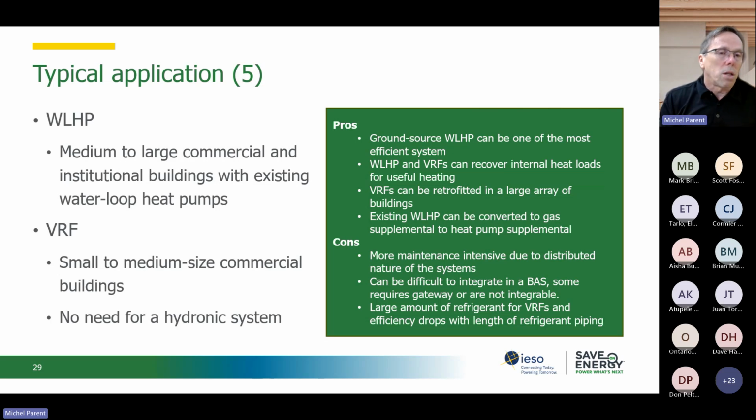So we have the pros and the cons for that type of application. A VRF system, by the way, the pro is really that it's a fairly easy retrofit. You don't pass water lines, it's just small refrigerant line. It does not do a whole building, but you can add multiple VRF systems. There are times where the VRF units are connected to a water loop to connect all of those exterior units together, if I can say. So there's a lot of configurations that are possible.